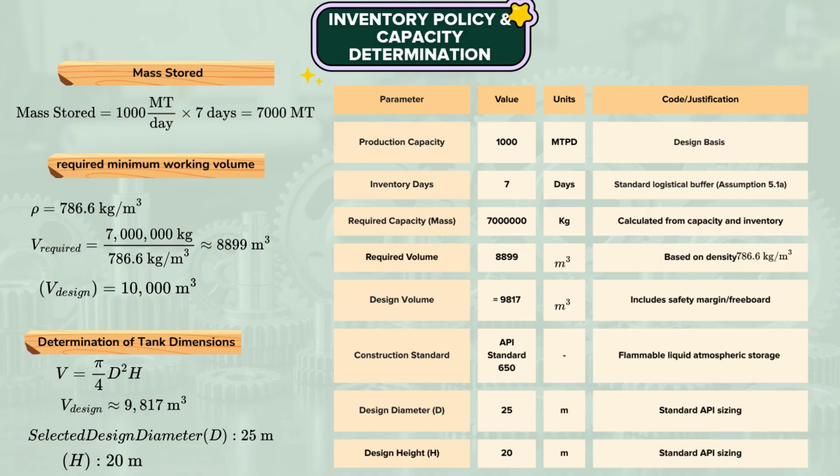are permitted. Carbon steel with specialized internal coatings is common, but given the critical nature of pure methanol storage, enhanced structural integrity and corrosion protection are necessary. API 650 tanks are typically constructed of carbon steel or, for superior chemical compatibility, stainless steel 316. The design must also explicitly incorporate cathodic protection measures and regular inspections, as methanol's properties increase the risk of galvanic corrosion. Furthermore, due to methanol's wide upper flammability limit, 36 vol%, the design must include robust vapor control and